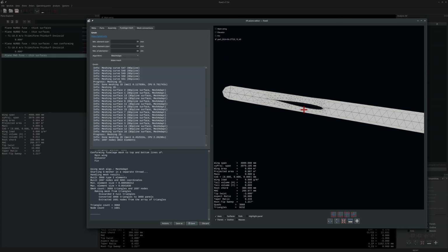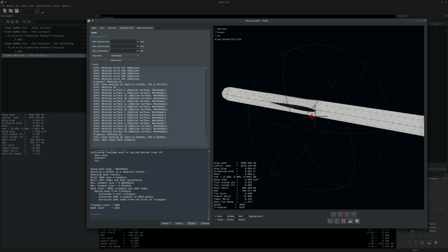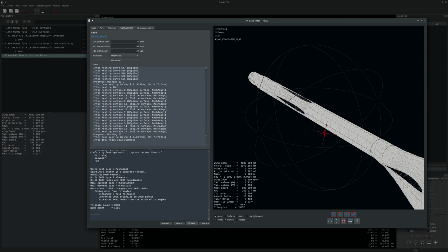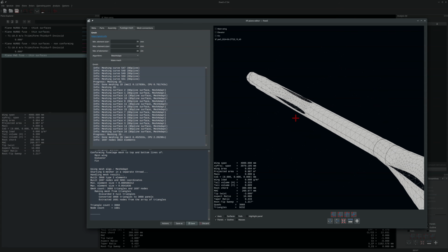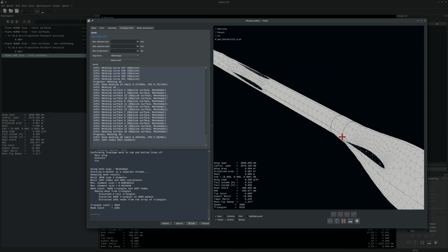So, yeah, again, I'm not sure what happens because I'm not an expert by any means in these matters of CAD software and meshes, but my trial and error so far seems to show that the beam here has too small a cross section, and the edges of the CAD fuselage can be a potential problem, so you will have to work it out by trial and error.